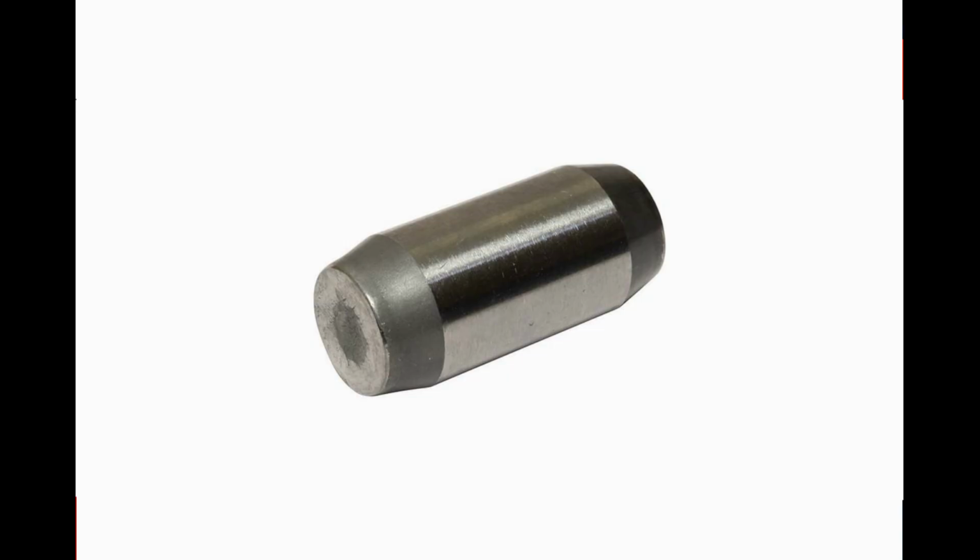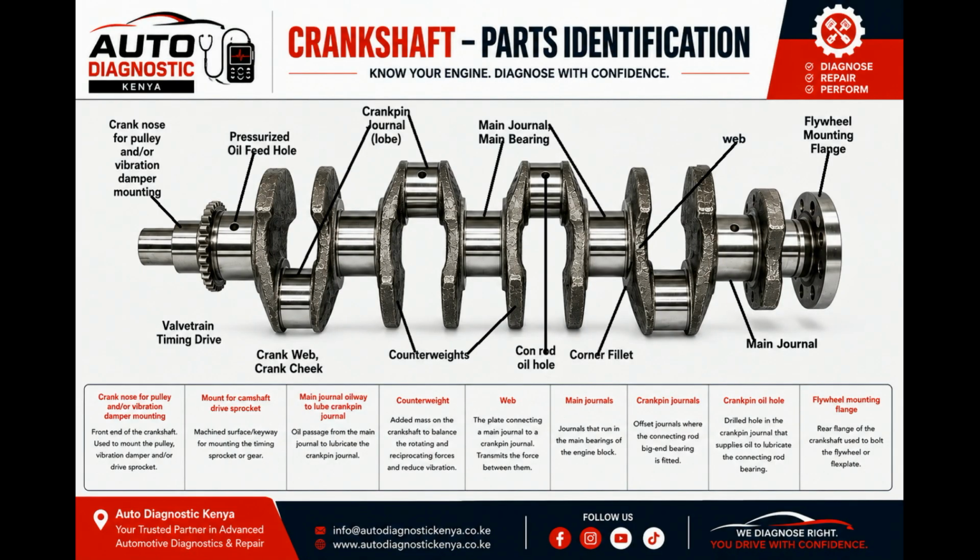Dowels help to take shear loads, and dowels or bolts can be arranged unevenly so that the flywheel can only be installed in the correct position. A locking arrangement is used to prevent the fasteners from loosening. So if you have ever wondered why manufacturers don't simply put equally spaced holes around the flywheel, now you know. The correct positioning matters.